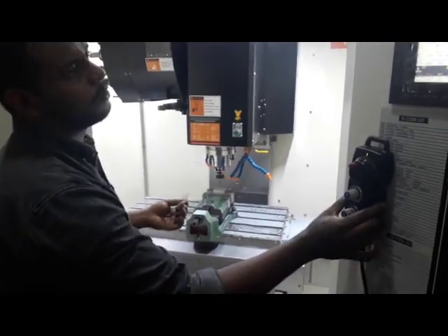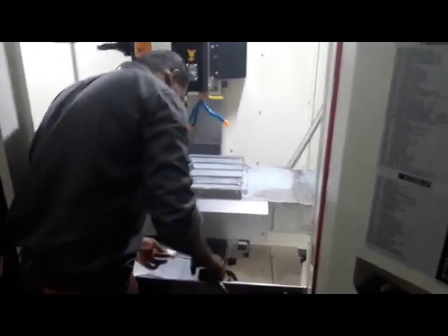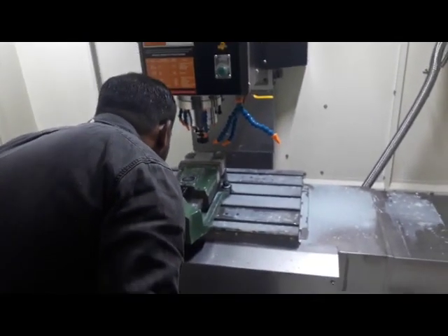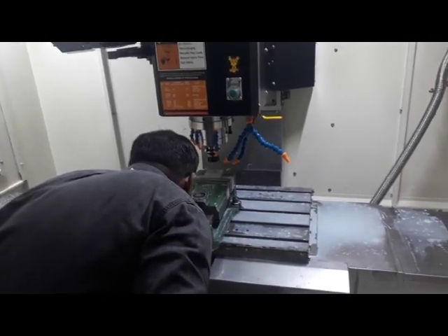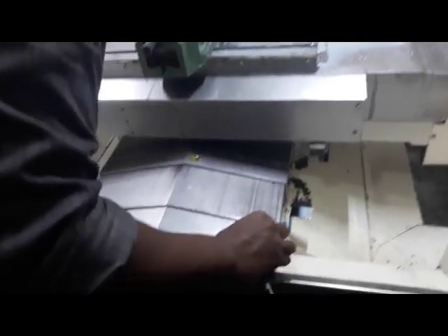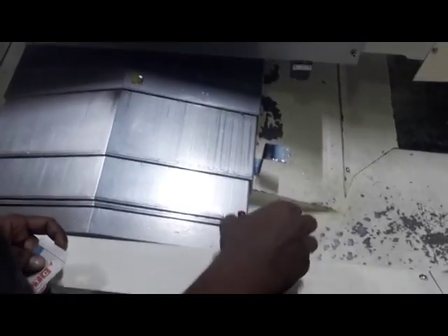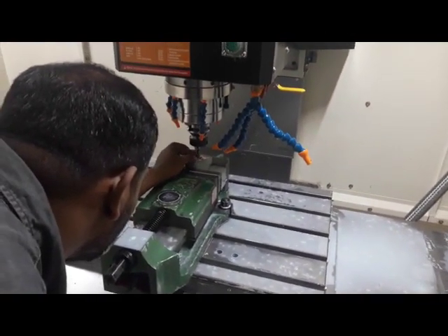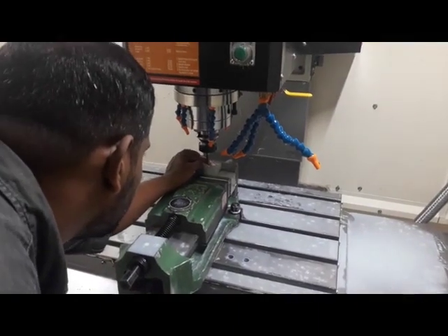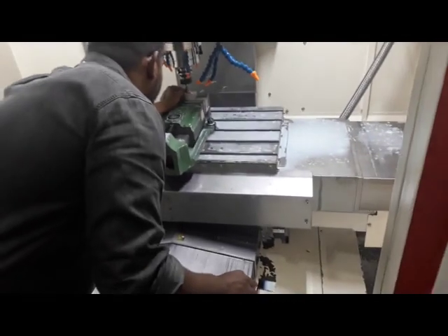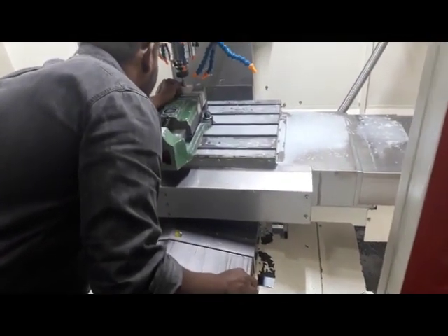How I'm going to do it is take the tool here to the part. I was on the 100 micron dial, now I'm going to go to 10 micron. Slowly place this paper on top of the part till I can feel it, till the time it tears off the paper.